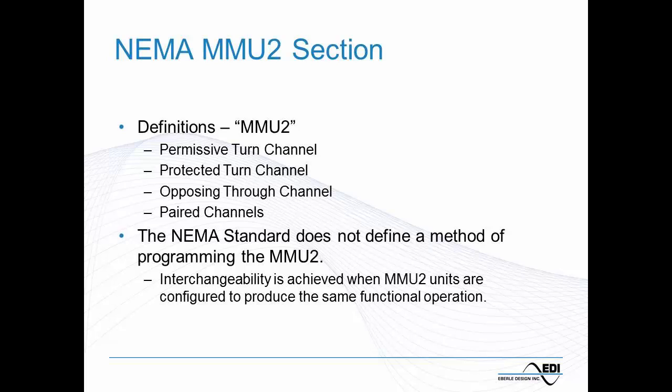So one detail to mention here, the NEMA standard does not define a method of programming the MMU. So different brands or different models of MMUs, like in our controller, may have different methods, different menus, different procedures or parameters for programming the MMU.